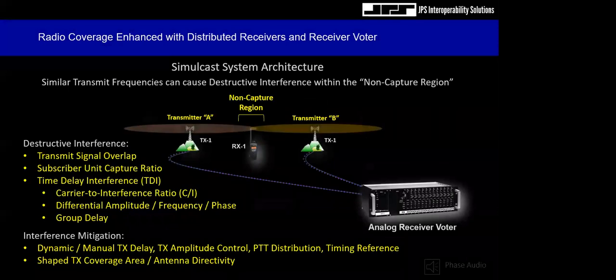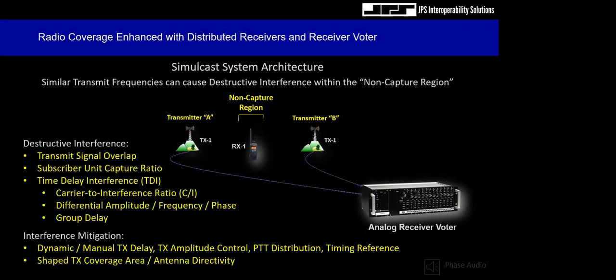Okay, so I guess you get the idea. The audio is legible, but it can be kind of disturbing because of the whining or the ringing sound. And if the phase is incorrect, greatly incorrect by 180 degrees with respect to each other, you can even cancel out the audio. So the launch of that transmit audio is very important in a simulcast system.